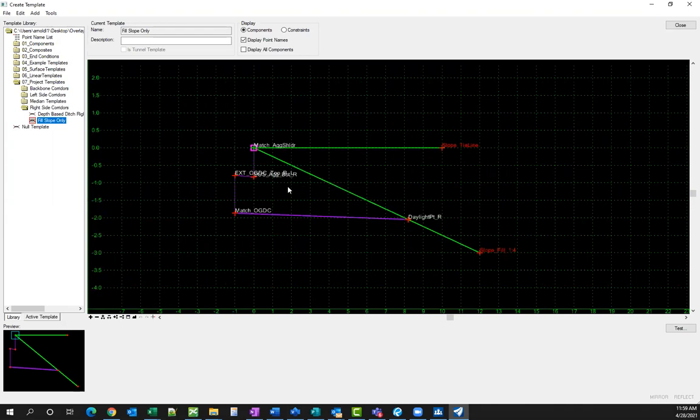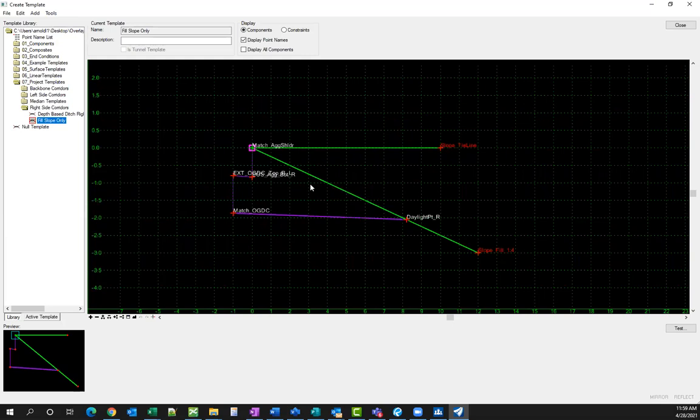But generally my strategy for end conditions, I don't know if I'll ever have a good strategy that really solves everything. End conditions, as I'm sure everybody knows who's gone through a project, are oftentimes the fussiest part of the model to get what you want. But generally what I do is I'll just have one slope. I might have a cut option and a fill option depending on the project, but you can control this even with just a parametric constraint. But I'll just have one slope.